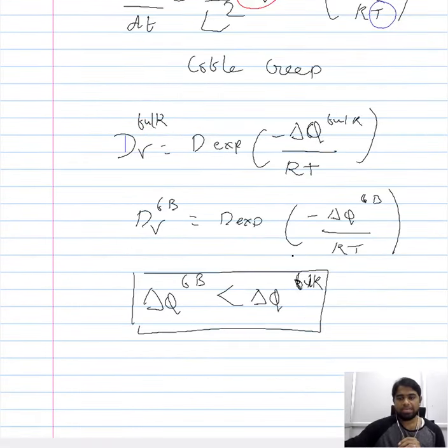So in this lecture we have talked about a new form of creep mechanism, referred to as the diffusion creep mechanism. As the name suggests, the critical role here is played by the diffusion of vacancies. This diffusion of vacancies is caused by the effect of stress, which introduces a difference in the concentration of vacancies.